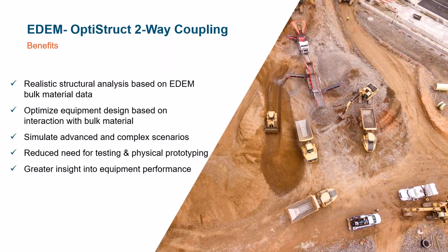With EDEM as bulk material software, more realistic loads can be obtained rather than worst-case hydrodynamic scenarios. Now when you couple EDEM with OptiStruct, more realistic structural simulations can be performed, which enables more optimized designs, and in return more savings of material.